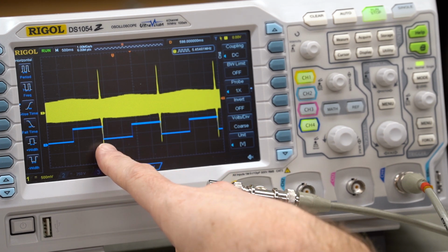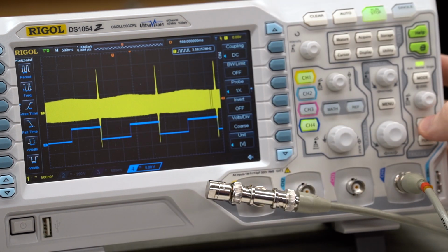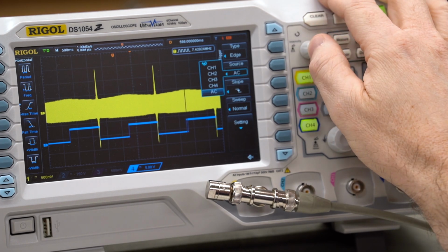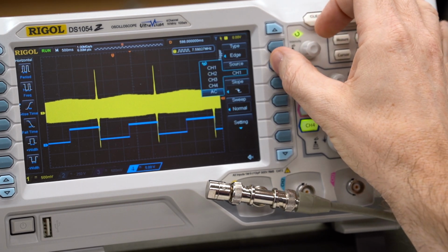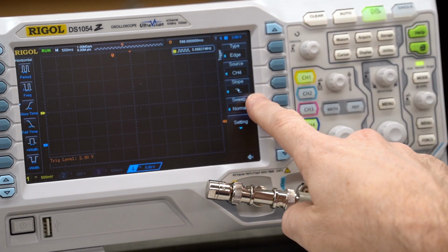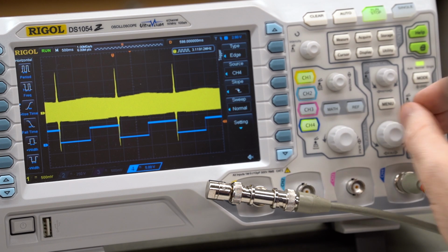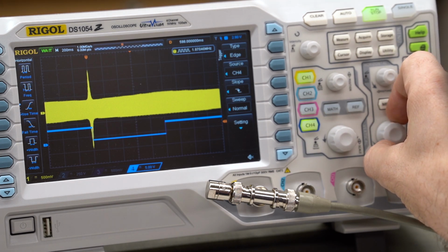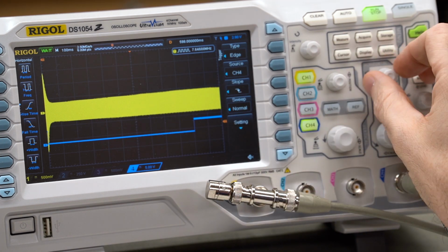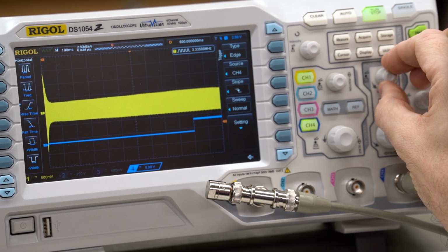If we trigger on the falling edge, we'll have our trigger point right at the bottom before it starts sweeping up. So I will switch my trigger source to channel 4, and I have it set to the negative slope, so you can see my trigger point is right here. I can scale this up. I just want to catch this one low frequency here. Scale that, and then I will move it horizontally so that it's over on the left-hand edge of the screen.